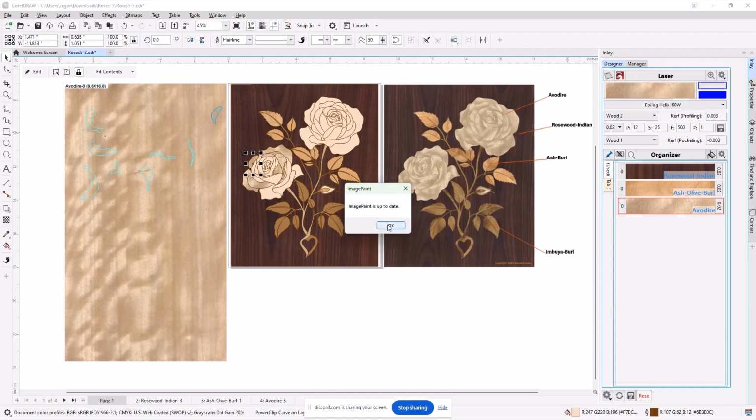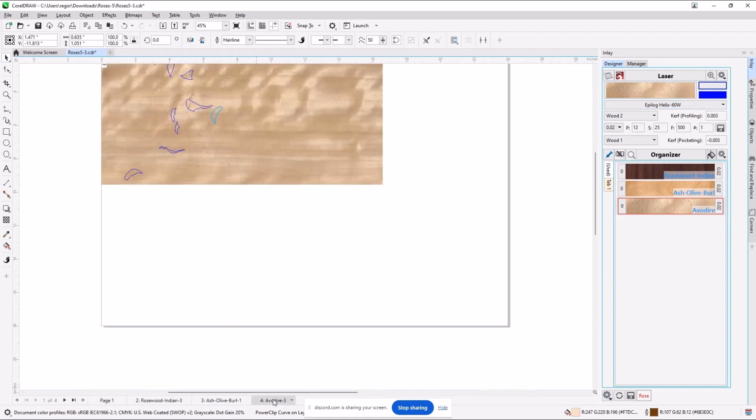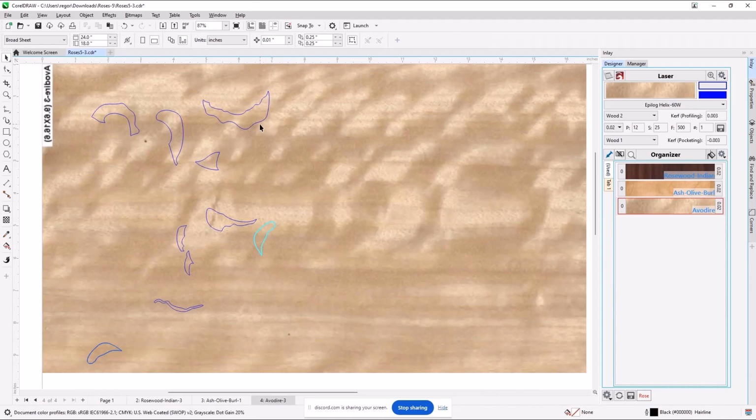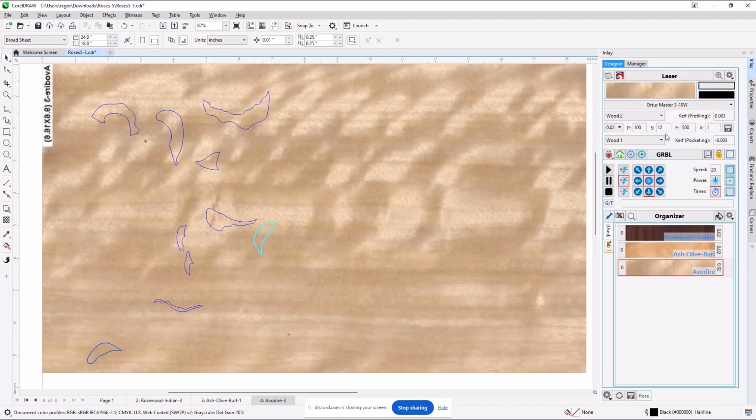So things due to the license need to be here. Things associated with the cutting appear here. So, for example, on this cut panel, I have blue chosen as the color. It shows up in here. I can see information about it. If I had chosen not the epilog, but I was going to cut it with the laser diode, I may find, in fact, I have a different color associated with it.